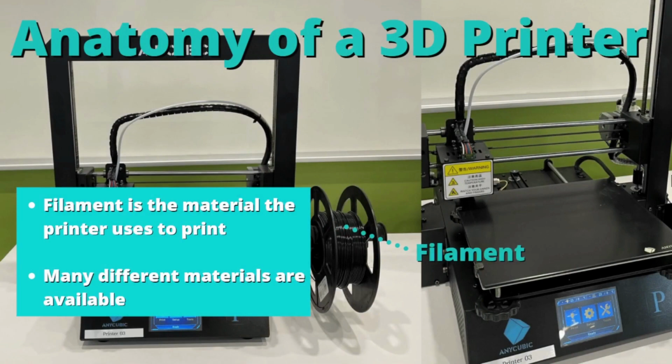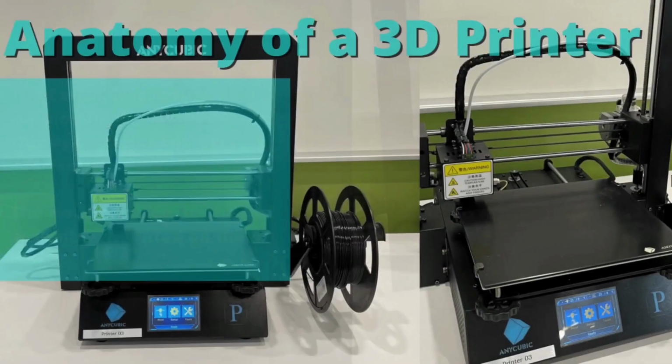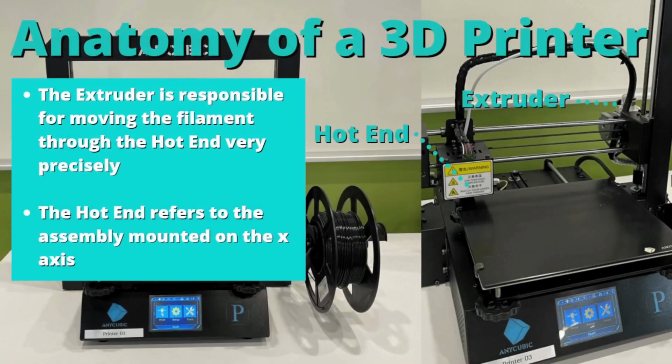Filament is the material that the 3D printer uses. No matter what the material, all the different types of plastics, they're going to come in the same filament form. Different colors are available. Wood-filled filaments, metal-filled, nylon, carbon fiber, just about anything you can think of. The extruder is responsible for moving the filament through the hot end very precisely. The hot end refers to this assembly that's mounted to the x-axis here. We'll go into that in more detail in a minute, but first we'll look at the extruder.